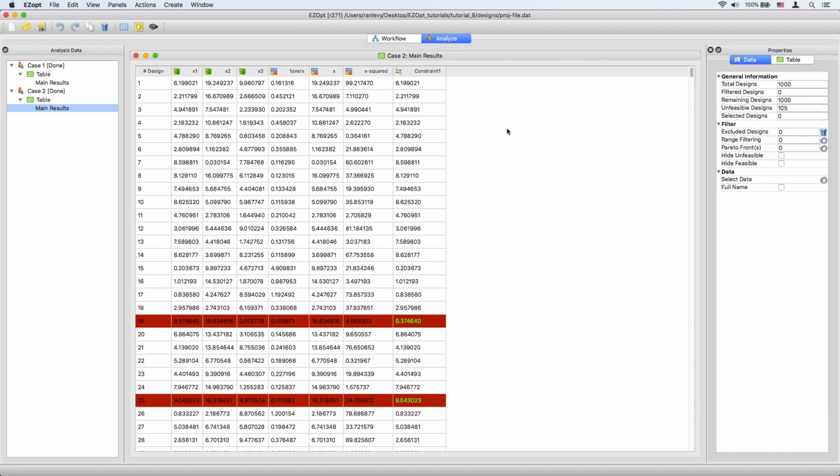While we can use any and all analysis tools to analyze the results of our runs, parallel coordinates and correlation matrices are a bit different. These two tools are usually used to analyze optimization process results, since their main focus is to show us how one or more parameters affect the values we set up as our target values. More on these tools in subsequent tutorials.